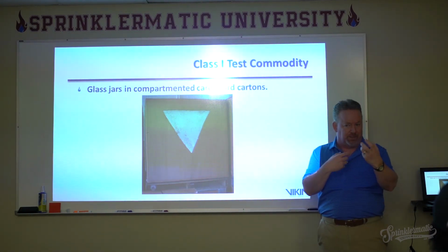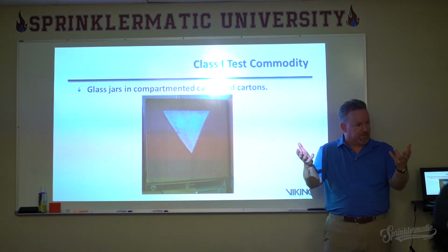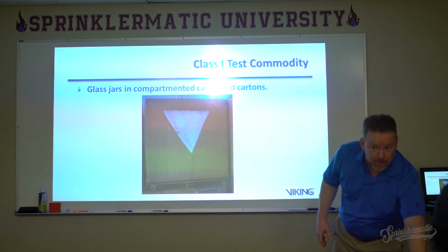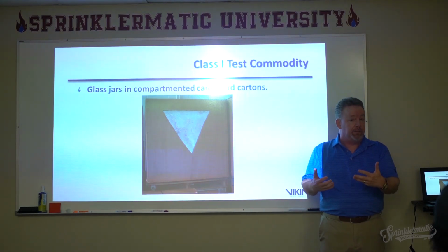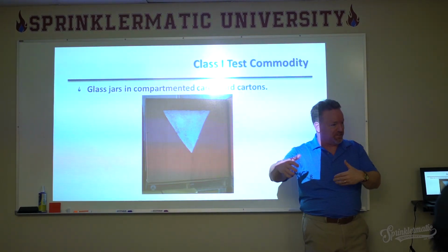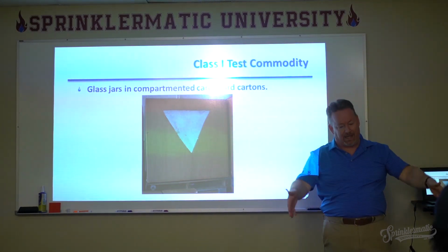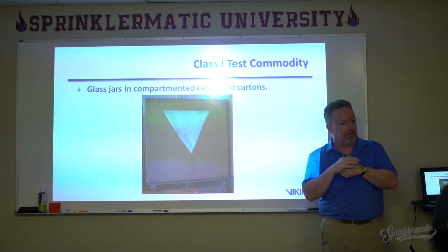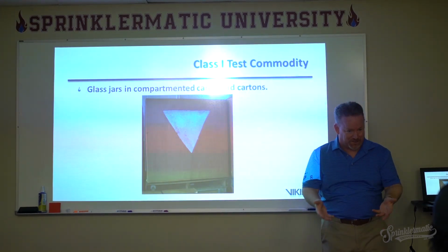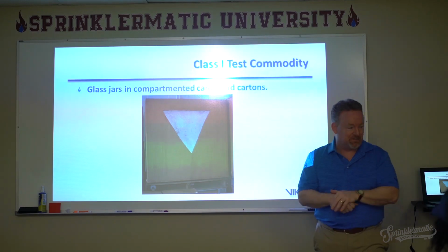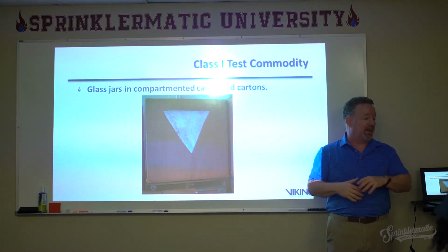So we kind of live and die on required delivered density, because then we're going to build out our sprinkler systems, and we're going to select sprinklers, and we're going to select piping, and we're going to select water, whether or not we need a pump or anything else on this system to deliver an actual delivered density, which is the water that comes out of the sprinkler minus the water that gets carried away by the heat, and it actually gets to the base of the fire. So what we've got to do is create an actual delivered density that can get through the required delivered density, delivering water down to the base of the fire. It becomes a challenge, but that's pretty much the balancing act that we're looking for.